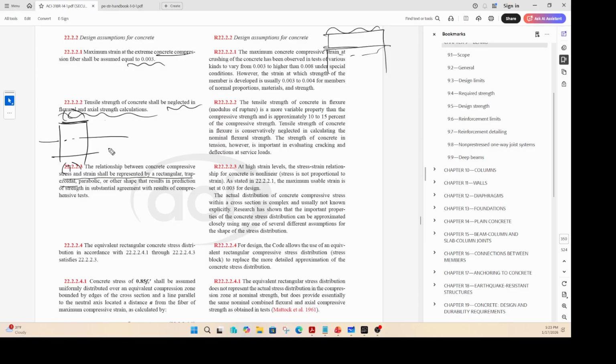If I plot the stress diagram here, let's say this is where the steel is. The actual stress diagram will look like a rectangle and a parabola. Then there's nothing here, and then you have your stress in steel here. So that is how the stress strain diagram will look. But because it is non-linear, it'll make life tough in terms of calculations. So there is something called a Whitney stress block, which makes some assumptions and makes the stress block a little more uniform, not as deep as this one. We'll talk about all that. And this particular value is 0.85 times f'c.